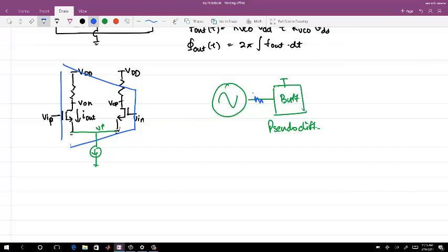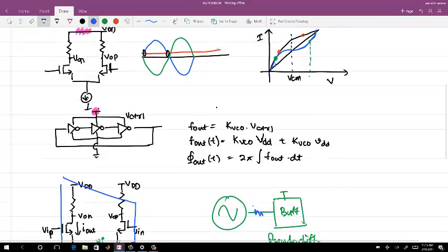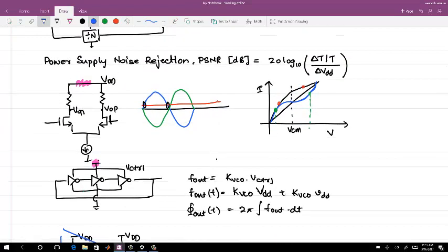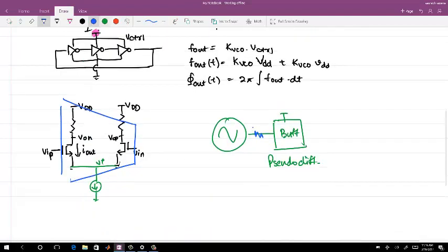Yeah, it will get shifted. So the output of the VCO, that's what we have seen here, right? The output of the VCO will get shifted with the common mode. Now, if you are applying this output of the VCO to any buffers, then surely you will see the duty cycle problem. But we do not do that because we always have an AC coupling cap here.